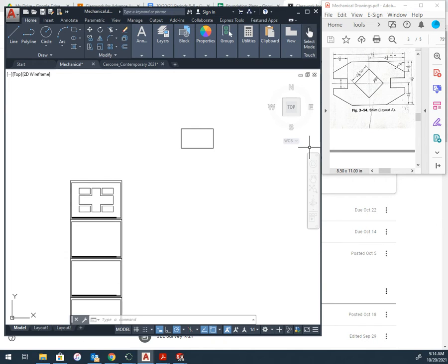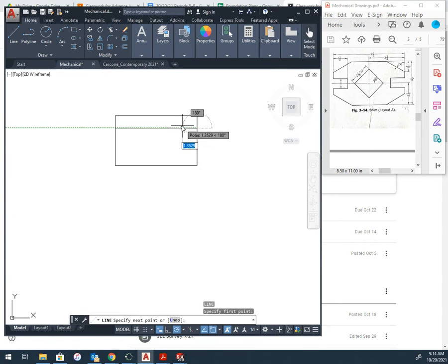Each chamfer has 2 dimensions. It should be a length and a length, or a length and an angle. This is 1 1/8 by 60. So I'm just going to offset this top line down, and then draw my line at 60 degrees. Well, it's 60 relative to this edge right here. So it's actually 150 on CAD.